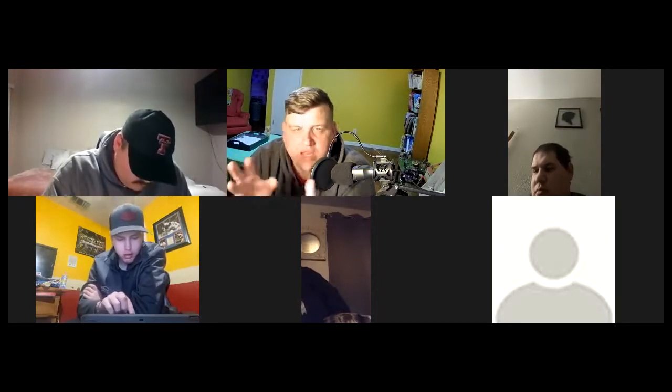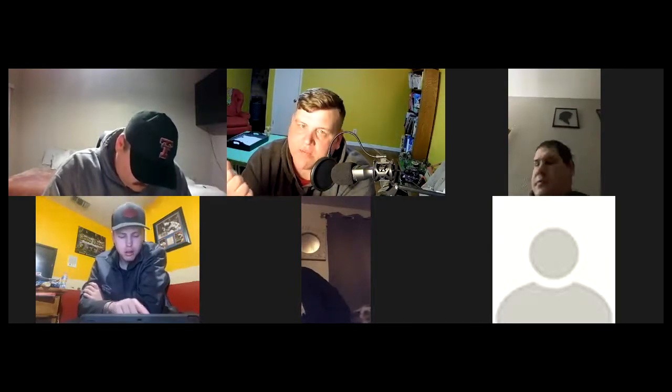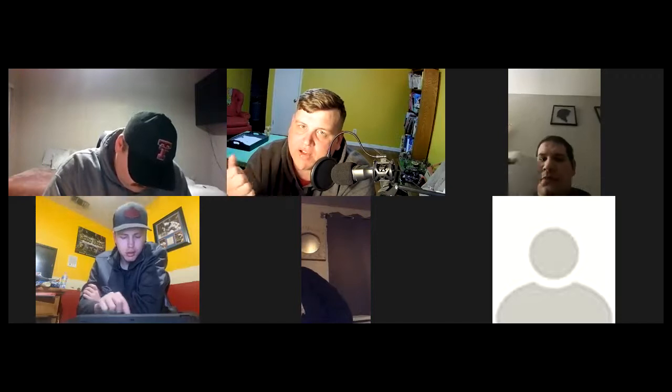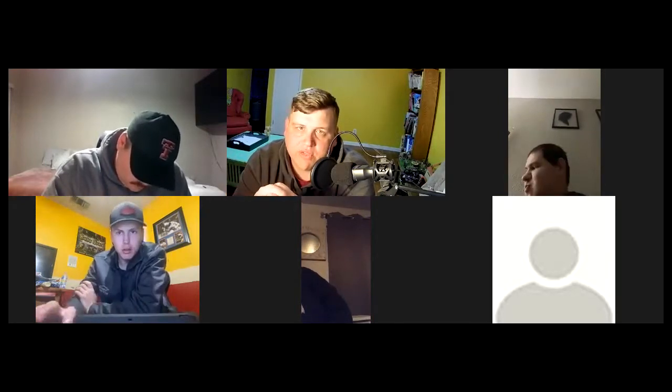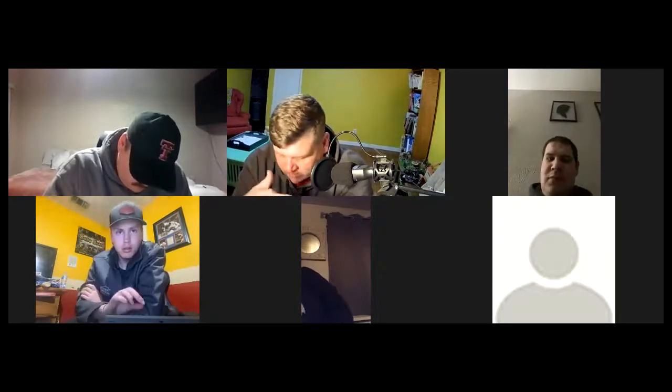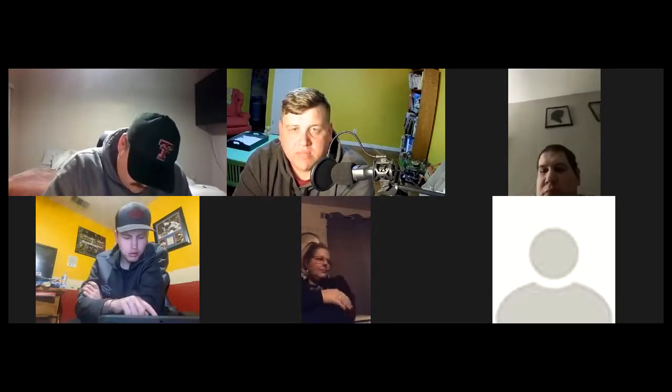Stage 2, like I tell everyone, when you put your camera up there and you're looking at it, you can twist your camera left and right and you get all the twinkles. I call it diamonds in the sky. When you get that, that's your stage 2 creosote. And then stage 1 is the loose coffee grounds. So we have 3 separate stages of burning.